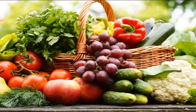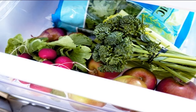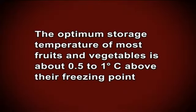Fresh fruits and vegetables are live products, and thus they continue giving off heat that adds to the refrigeration load of the cold storage room. The storage life of fruits and vegetables can be extended greatly by removing the field heat and cooling as soon after harvesting as possible. The optimum storage temperature of most fruits and vegetables is about 0.5 to 1 degree centigrade above their freezing point.